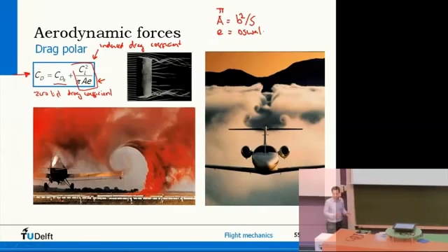It goes from 0 to 1, and the better you've designed it, basically, the better you have a lift distribution along the wing, the better this Oswald factor E will be. So we have this parabolic drag polar. I call it parabolic because it's a parabolic function with a squared. And this is basically the only equation you need to know from aerodynamics to solve flight mechanics questions.